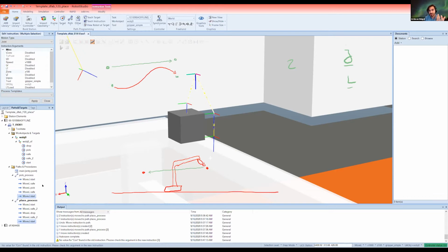When I say the robot tries to move, I mean that it tries to move the TCP, or its end of tool, linearly between these two points. If one point is on one side of the robot and the other point is on the other side, the robot tries to move along itself and collide with itself. So it's not possible. The robot gets a configuration error, a self-collision error, and it's not going to do the job.